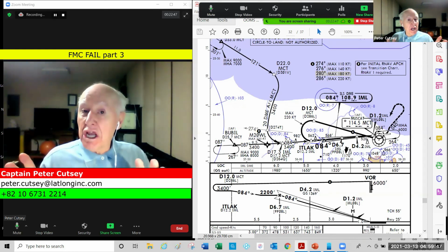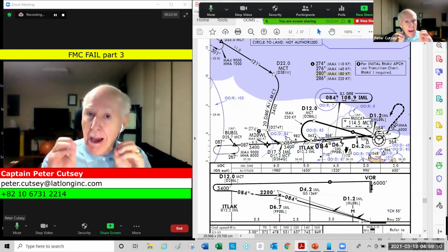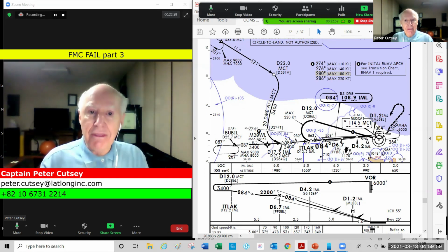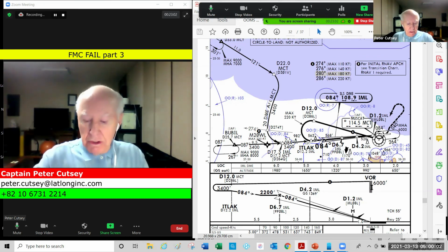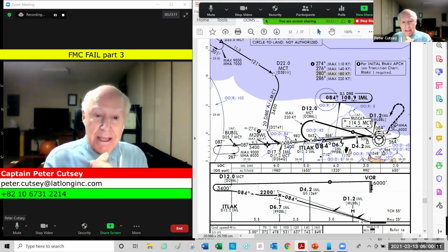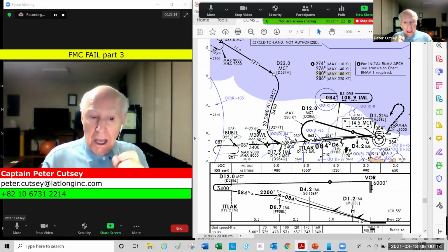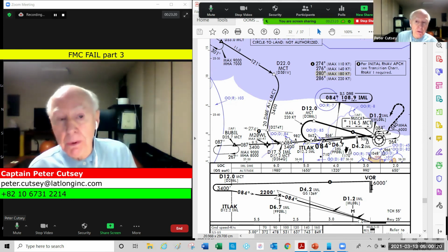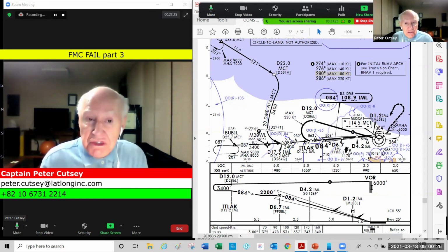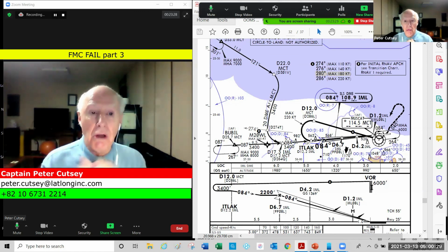There's got to be a great coordination between pilot monitoring and pilot flying. Remember, pilot flying, you focus on flying the airplane. You're using the auto flight systems. You're using the auto throttles. So fly the airplane and try to do it in the fashion that I just briefed you on. And you'll find that this procedure works out absolutely beautifully. And remember that you've selected approach so that you have the proper picture of the expanded mode for the approach mode or the center mode, and the auto flight systems will handle the aircraft. You're going to do all the thinking.